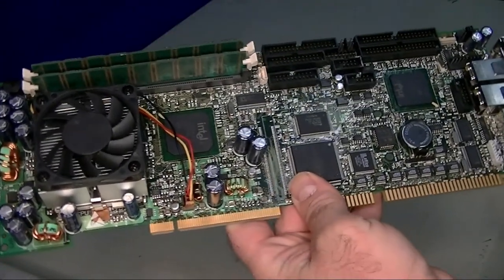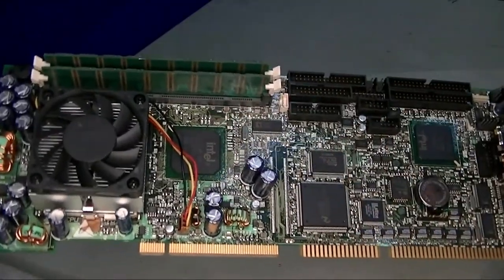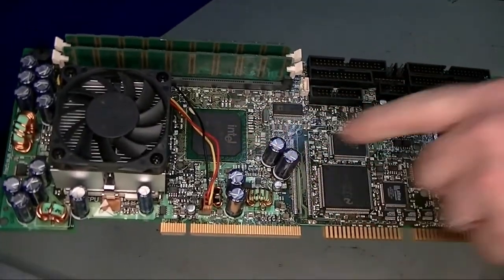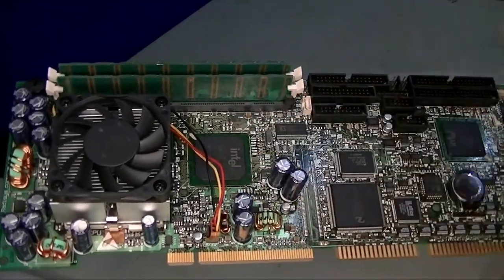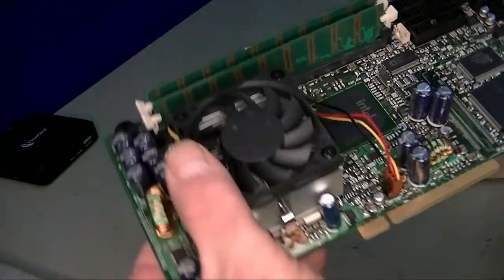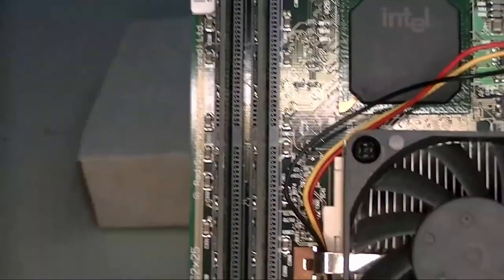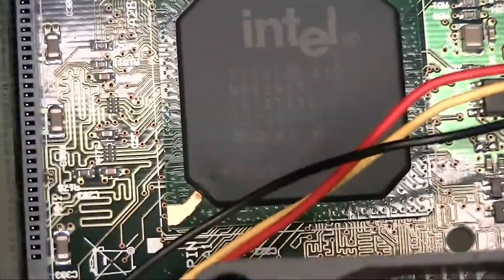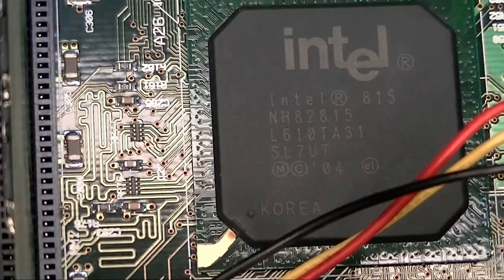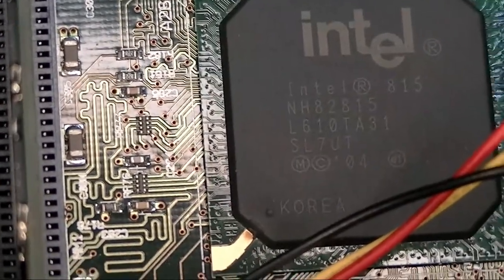but getting flipped around to the other side, we have the support chips, and by the positioning of this chip to the CPU and RAM, this is going to be effectively the Southbridge chip. And even in this instance, it's old enough to where it doesn't require a heat sink. And let's zoom in. I didn't bring over my reading glasses. Let's try and zoom in. Okay. So that's the 815 chipset from Intel. Even has an S spec. The SL7UT is the S spec.